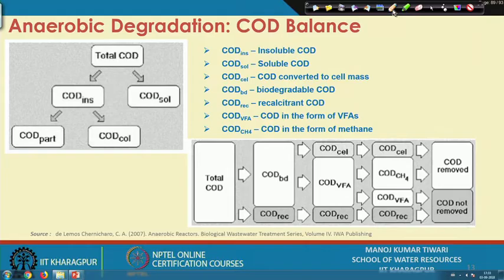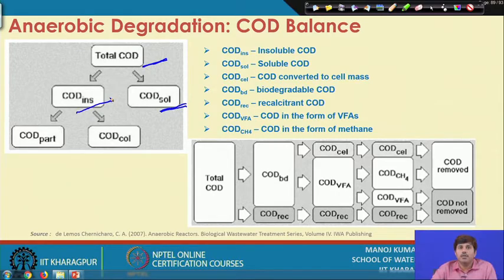So, the total COD that comes into the system may be of two forms. There could be soluble COD, which is the amount of organic matter dissolved in the water, which, if you filter it, will pass through the filter. Then there is insoluble COD, the concentration of organic matter which is not dissolved in the water, which is in a suspended or insoluble state.